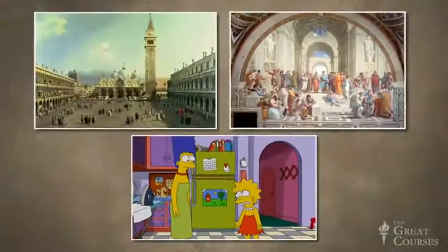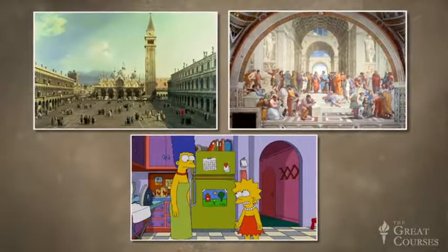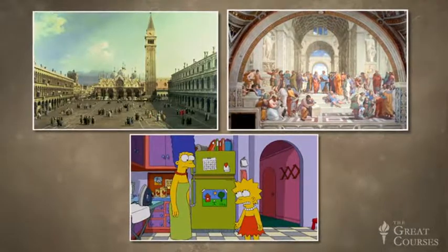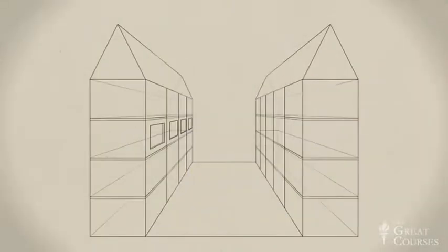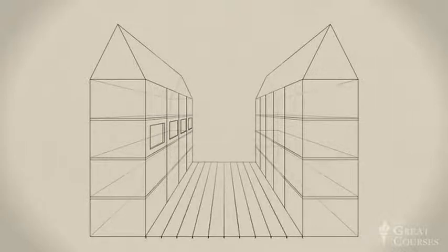In all three examples, a pattern based on a grid recedes along the ground plane. We'll add one now in the open space of the quad. We'll start by dividing the front edge, the very first line we made, into 10 1-inch increments. Next, we'll vanish these back. Try adjusting the pressure as you draw these lines. Greater line weight forward, less as you recede.